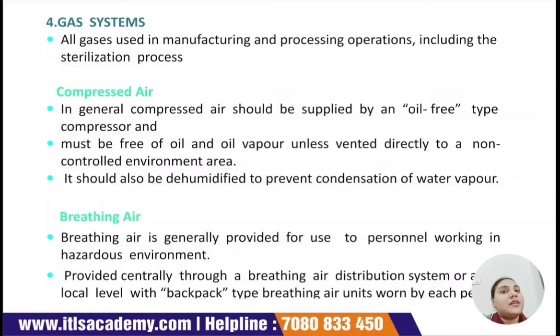In any plant, the compressed air is vented off or disposed of, so it is very important. Firstly, the compressed air should be supplied by an oil free type compressor, and it must be free of oil and oil vapor unless vented directly to a non controlled environmental area.